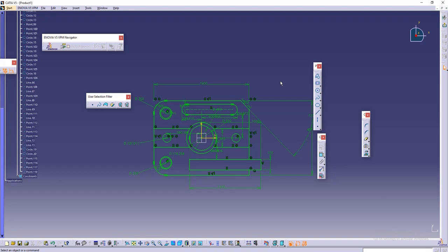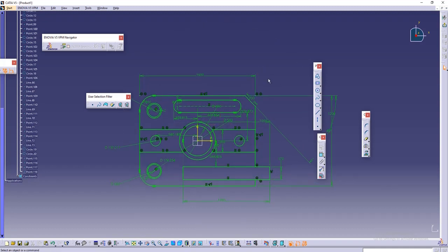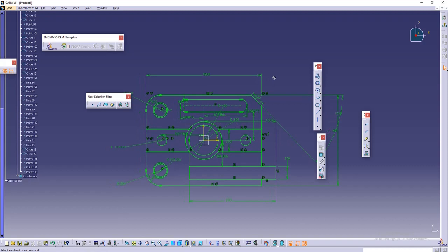Because once we start solid modeling, you will understand it is very difficult to get reference dimensions from each thing. If I just extrude it and I don't know the dimension of this and this, or the reference with this, it will be very difficult to create the different parts. That's why when you create a sketch, always give some references here. It is a little difficult in the early stages, but once you understand the usability of constraints and why they are very important, you will learn.